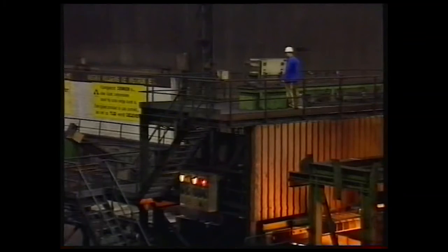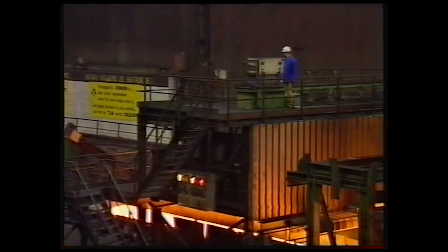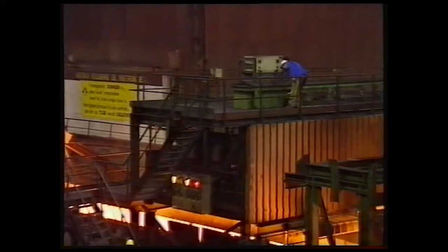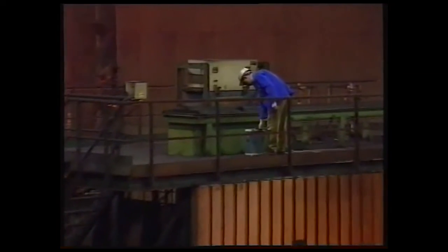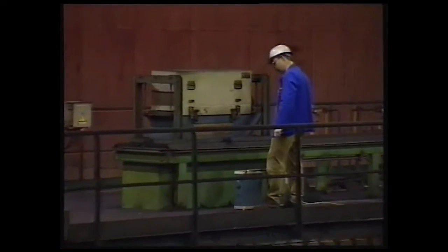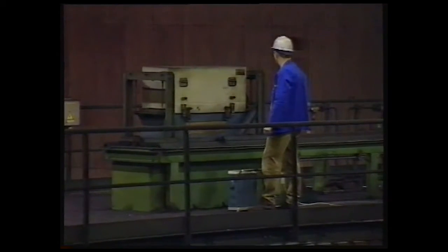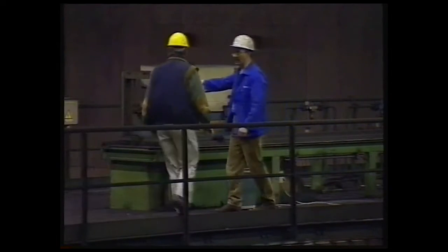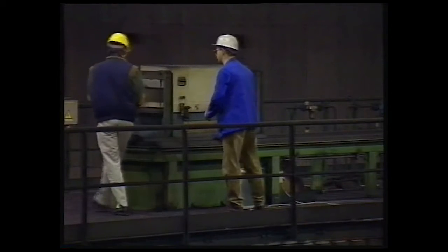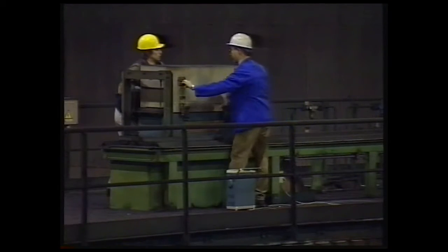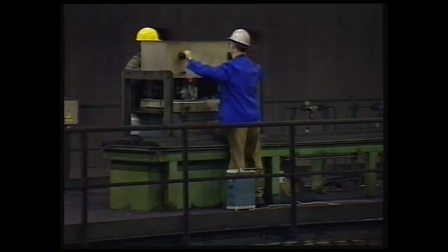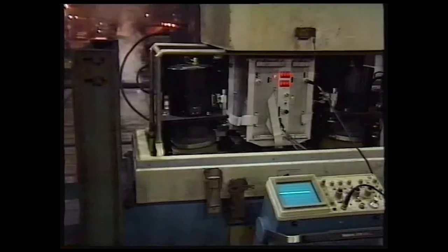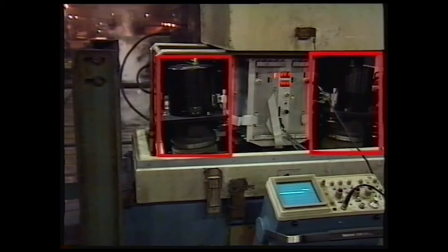The vision system in the hot rolling mill continuously monitors the passing steel plates. As mentioned, it measures their thickness and determines optimal crop position. Here we focus on the width measurements. The vision system uses 2 linear CCD cameras of 2048 pixels. Each camera takes an overhead view of the steel plate. In this harsh environment, the cameras require cooling and monthly recalibration.